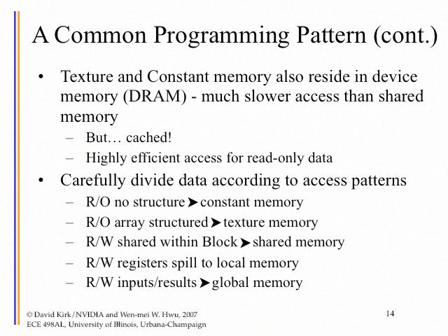And then the registers, you don't really explicitly use registers, but all the local variables that you declare in the device functions get pretty much automatically assigned to registers until they run out. Whenever they run out of registers, you get into serious trouble. Okay, so that's one of the performance cliffs. And I'm going to come back to this point.